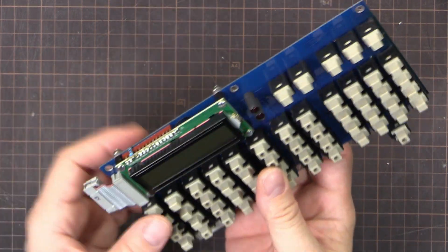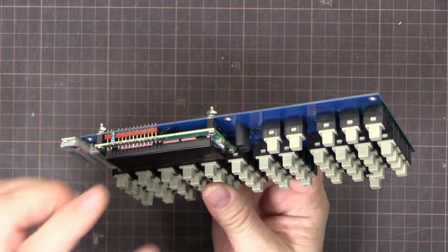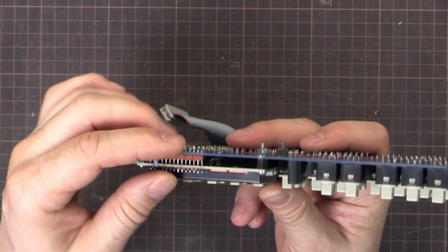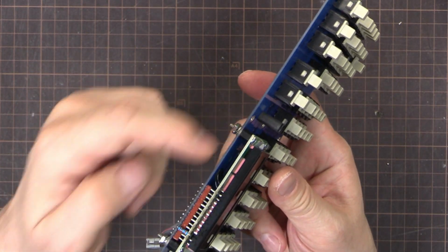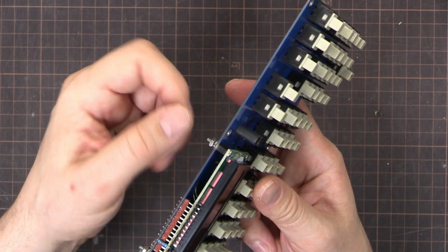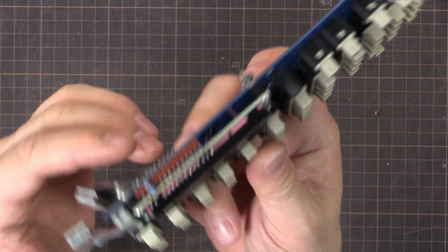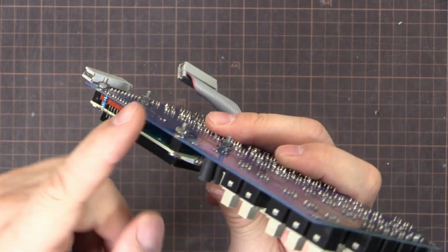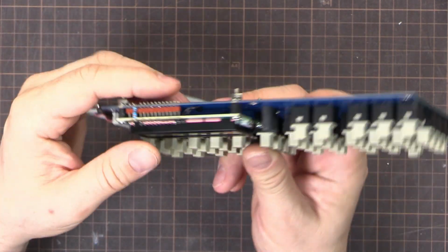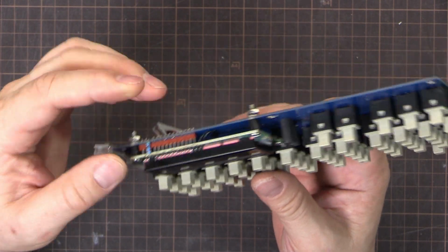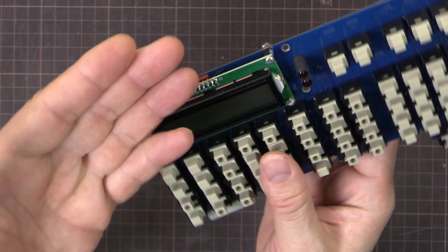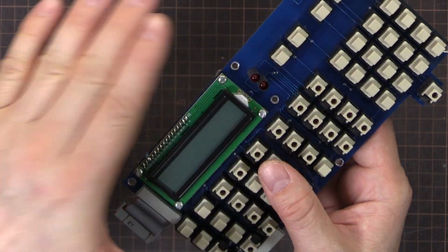I did find there's a few modifications I have to do, nothing too major, but the first one is that the new screen is actually 2mm thicker than the old screen. So the old brass standoffs are 8mm tall. I had to replace those with 6mm ones. I just used nylon standoffs there. Straight in, I used threaded ones. I just drilled them out to 3.5mm or so. But yeah, any sort of standoff that's 6mm tall, 4 of those, and that will bring that screen down so it's at the original height.